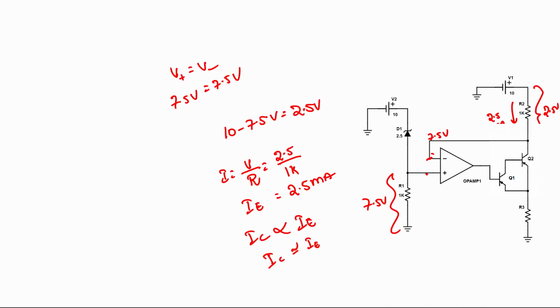If I want to calculate accurately, we have to look into the datasheet, and that depends upon what type of transistor we are using. Generally, the gain alpha value will be somewhere around 0.99. So, if I multiply with alpha, then we can easily find out the IC value too. Since our intention was to find IC, I am considering IC is also almost equal to IE.